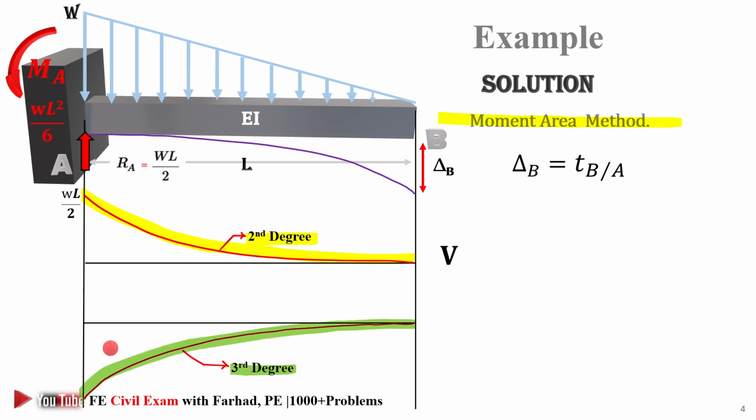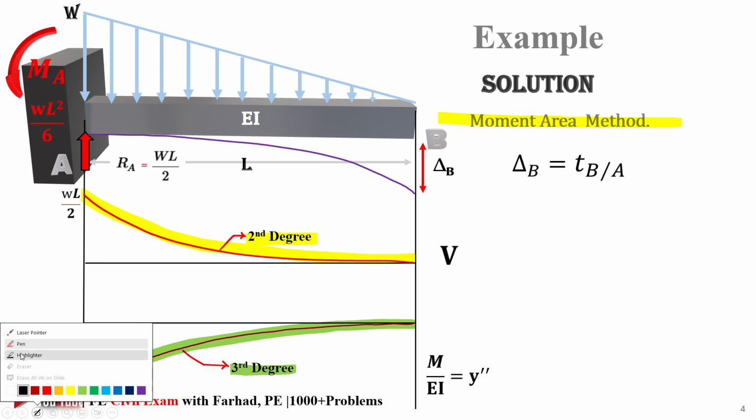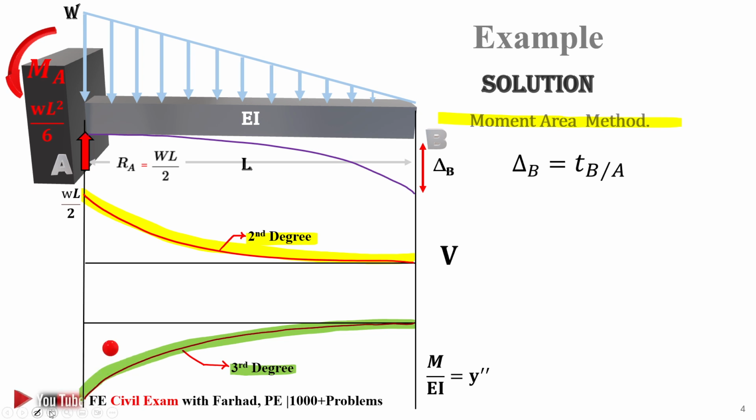If we divide it by EI, you can easily see this is third degree. We have a rule: if this is L, the distance to the centroid from the base is L over n plus 2. So that's L over 5. And if this is L over 5, the other part is 4 over 5 of L.